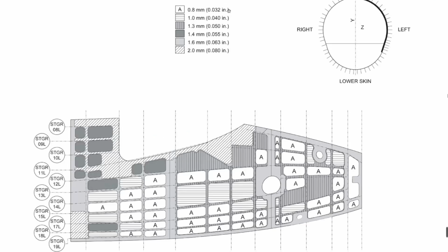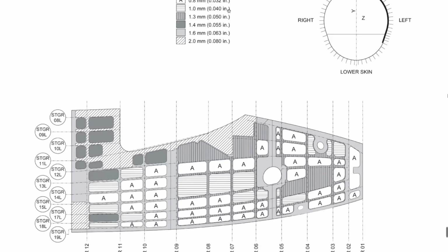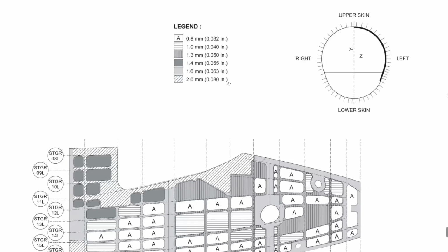So if you have a scratch, we said this scratch we have to blend out. When we blend out, we remove part of this skin thickness. So we have restrictions. This is what happened in my case with these structure guys when they started to blend out, but it was not on the left side, it was on the right side, I think, anyway.